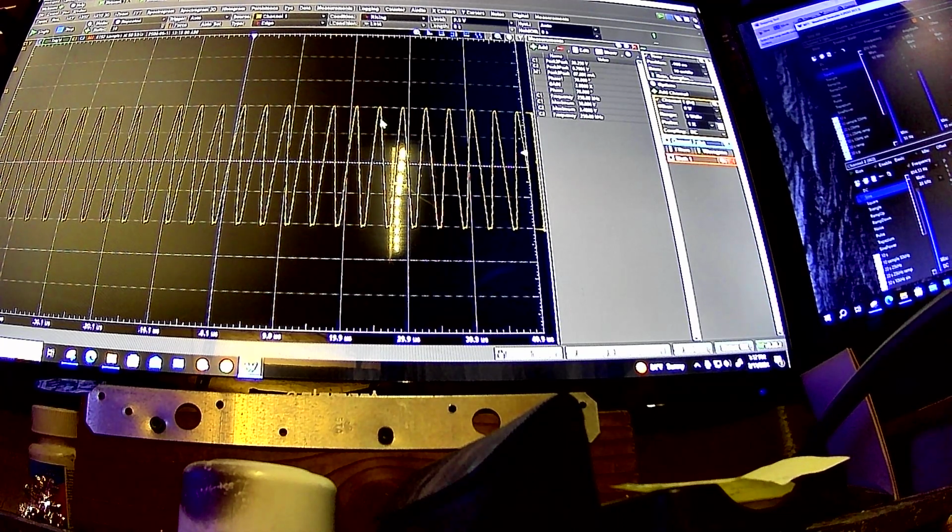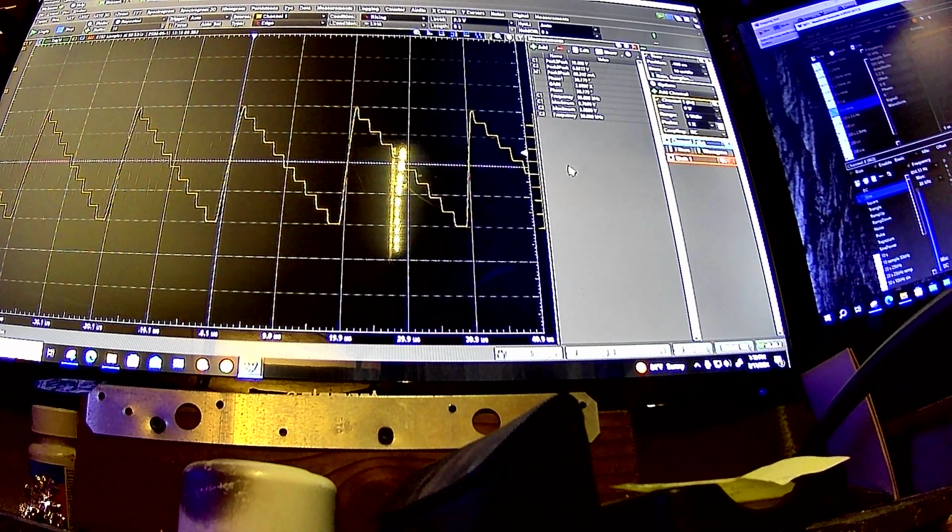Because this is at a 250 kilohertz rate. Like I said, this is the maximum signal you can generate, and it is generally slew rate limited. Because of that, you can filter above 500 kilohertz at your corner frequency, and that'll get rid of most of that jagginess we are seeing over here.